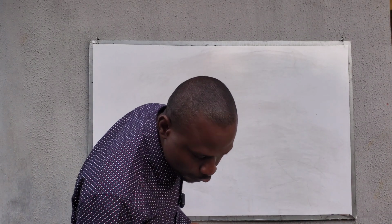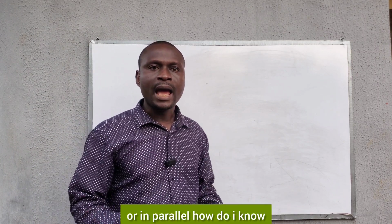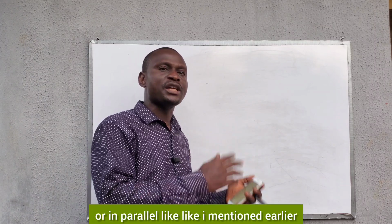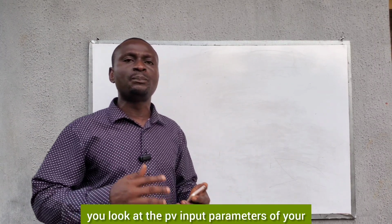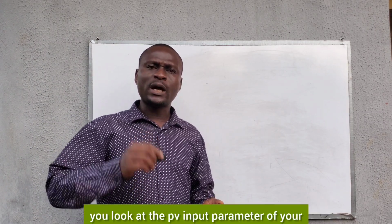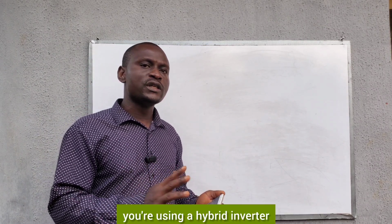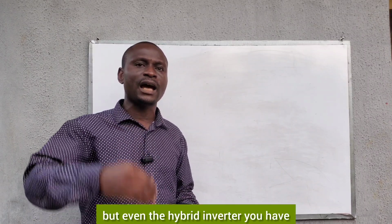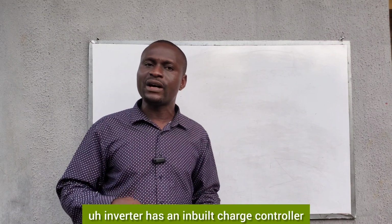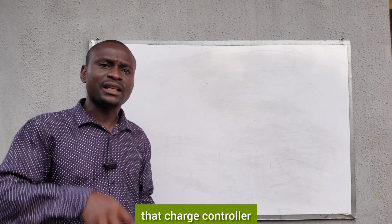Question number 6. How do I know when to connect solar panels in series or in parallel? Like I mentioned earlier, you look at the PV input parameters of your solar charge controller, not the inverter, unless you're using a hybrid inverter. But even with the hybrid inverter, you have the solar charging parameters, because the hybrid inverter has an inbuilt charge controller. So you are looking at the PV input parameters of that charge controller.